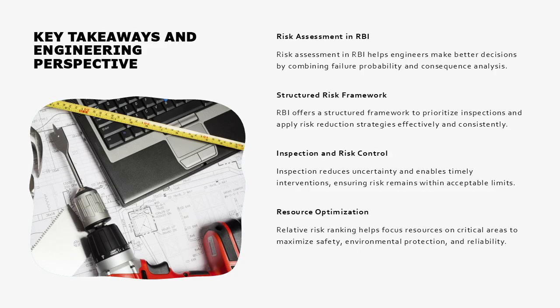The key takeaway from this presentation is that risk assessment in RBI is a practical engineering tool designed to support better decisions, not to predict failures with absolute certainty. Risk is defined as the combination of probability of failure and consequence of failure, and both components must be understood to manage equipment integrity effectively.